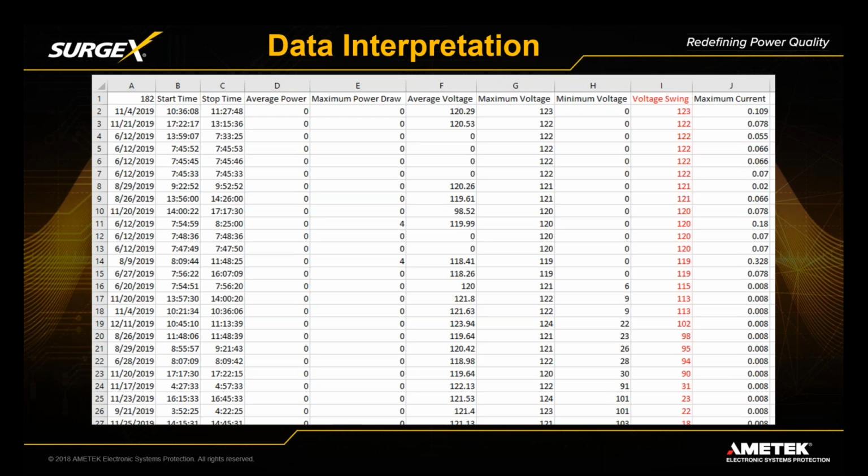Oh, no, that's great. So usually when I'm doing an analysis of this, I'll start with that voltage swing column. I will put it in order of maximum to minimum, and I'll page down and see where the voltage swing starts to get below 10. To me, if you've got a 10-volt swing within a 30-minute window, there's something going on there. And sometimes that 10-volt swing is still within ANSI standard regulations, right? It's still between 110 and 124. That's a 14-volt swing, so you could have a 10-volt swing and still be within spec. But the fact that it is moving...